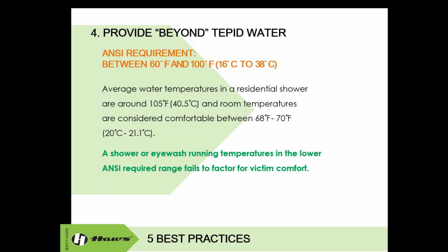Imagine yourself, 15 minutes is an extremely long period of time, especially if that incident might have been extremely severe. You're holding your eyes open with running water in them. You have a 20-gallon per minute shower cleaning off those contaminants. We need this to be as comfortable as possible for that victim.